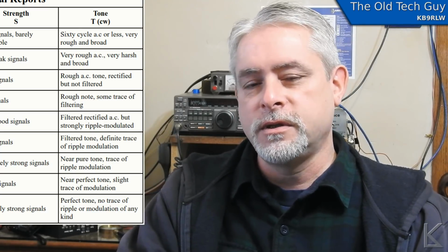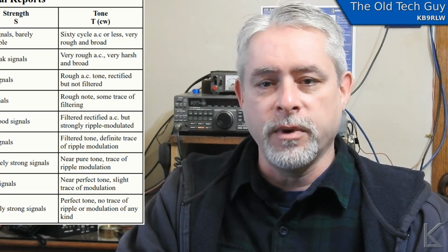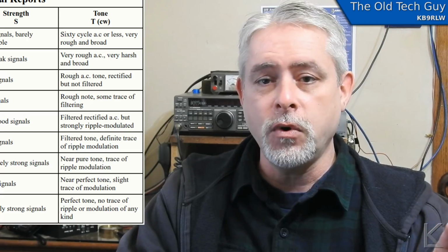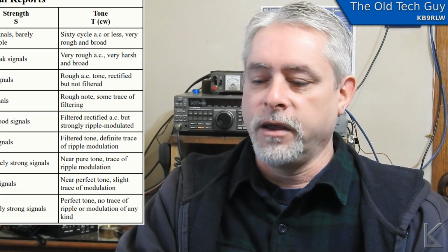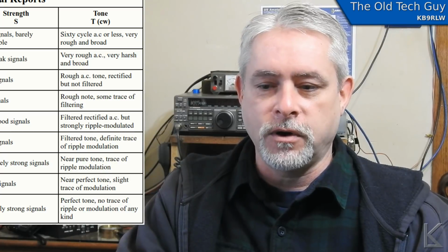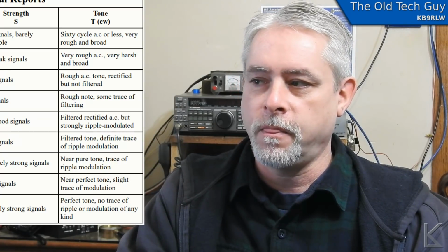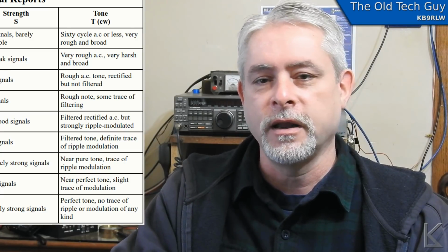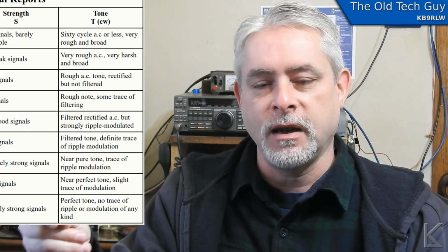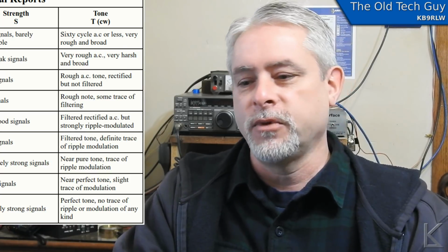Under load, you'd still get some ripple through there, and it would give your CW note a hum, a 60-cycle hum to it. Instead of a boop, you'd hear a whoop, kind of thing. There were key clicks. If your keying was too harsh, if it wasn't filtered or you were switching with too much current, you'd get a little pop at the beginning of the note, a little click right at the beginning of the note. And a lot of harmonics would come with that.